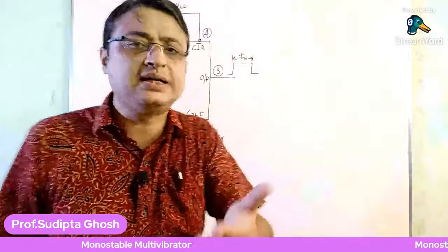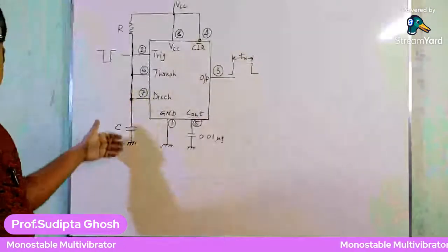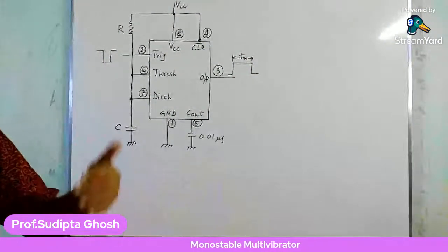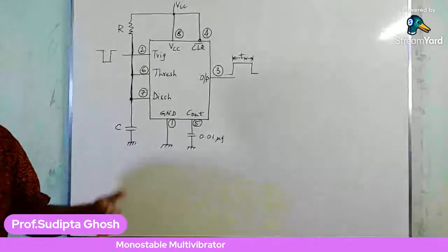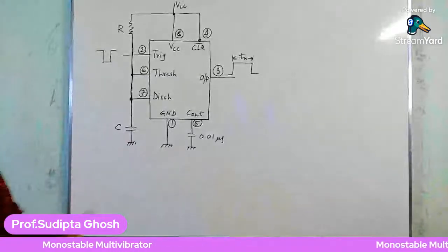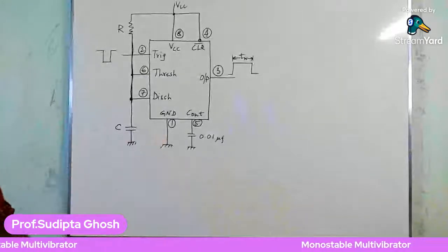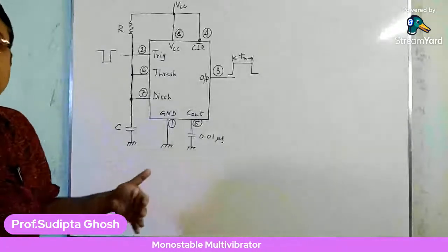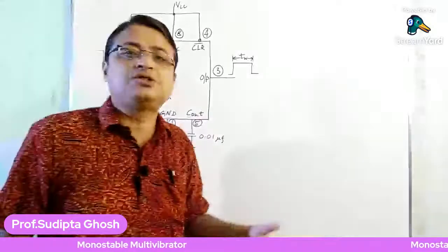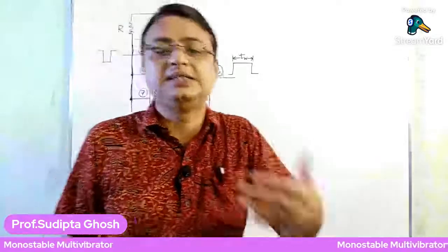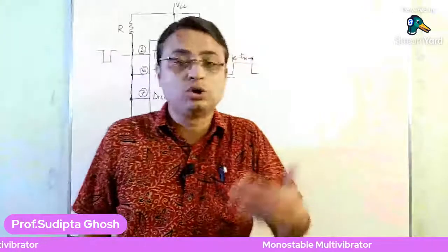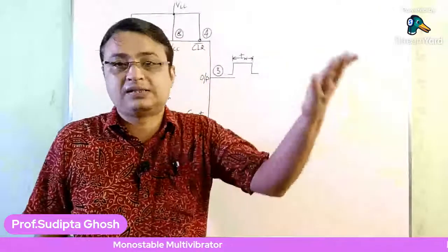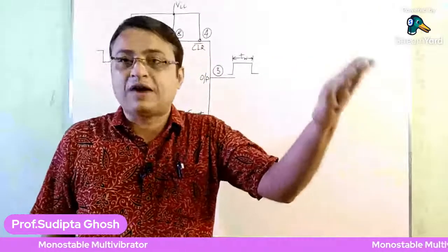Now consider that while charging the capacitor, if the capacitor is initially discharged, that is if the capacitor voltage is 0 at time t equals 0, and then after switching on the circuit, the capacitor tries to charge itself, that is the charge inside the capacitor goes on increasing, it starts from 0 and it will end at the value of 5 volts.